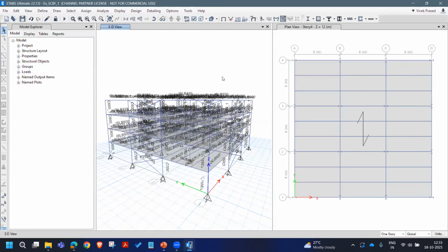But you can see the nonlinear behavior of the members, which were designed using a linear static analysis. This can be studied here. We can extend this further for a time history analysis that will have the full lateral sway, positive and negative, and then members can fail differently. I'm stopping this at this stage.